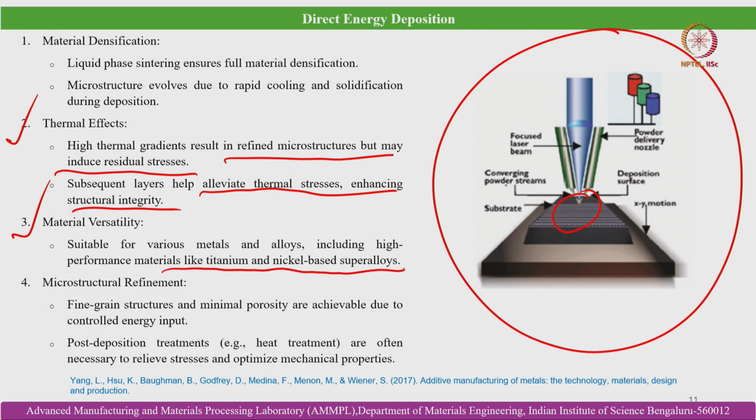Okay. And also in situ alloying is possible in case of DED in a much more effective manner than we can get in case of LPBF. So, you can see these hoppers; you can use 3 different powders, say A, B, C. Then you can deposit them sequentially to facilitate in situ alloying and also to generate functionally graded parts.